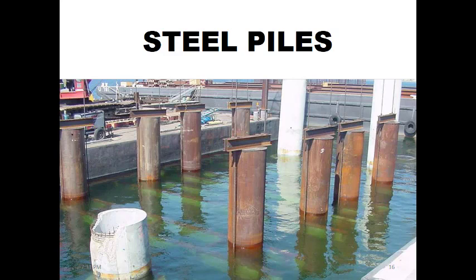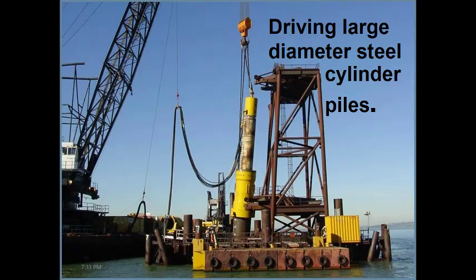But when it reaches that piece of rock, it will start resisting. And if the operator is not careful, they may break the pile. It can break either the bottom part or the top part, depending on the practice that you exercise during the process of driving the pile.